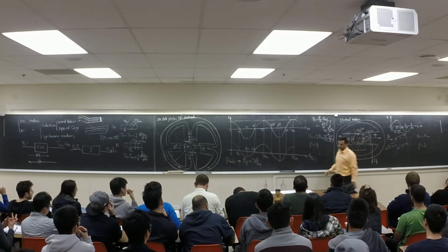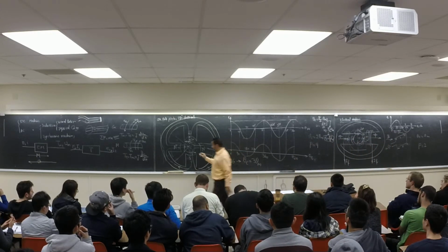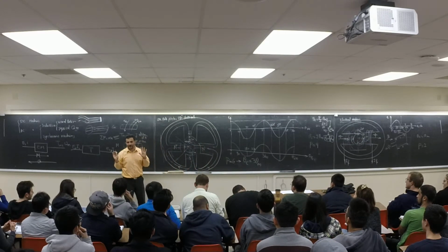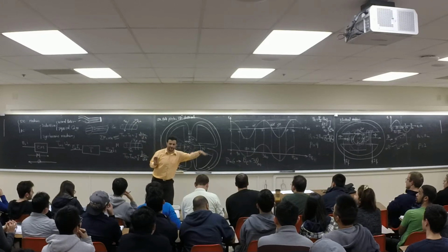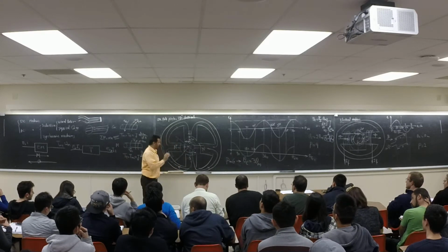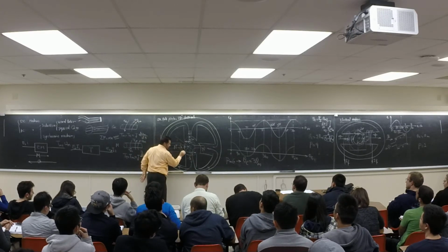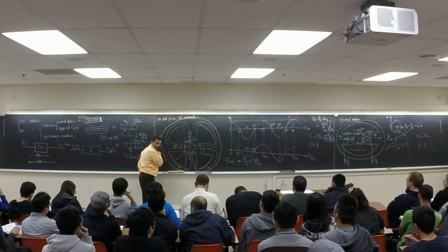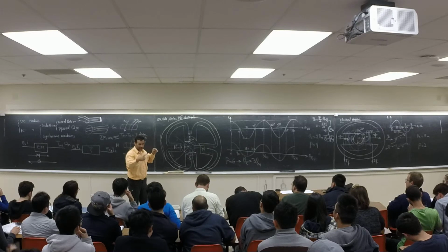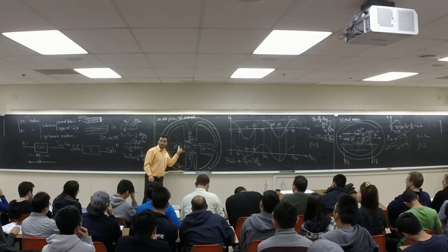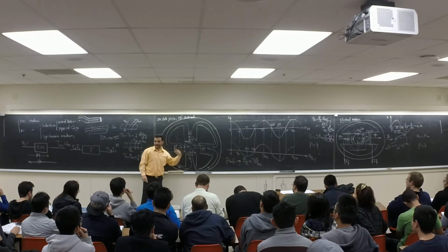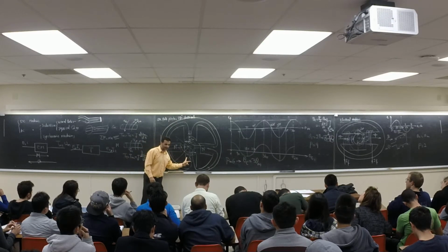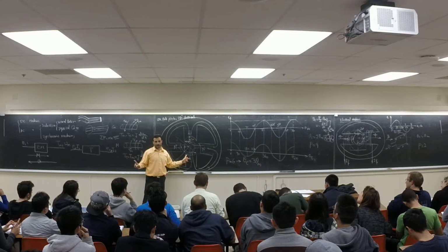How much is the pole pitch here? It's still 180, see, all the time it is 180 electrical. You go from N to S, right? 180 electrical. I'm going from here to here. How far did I go electrical? I went from N to S. N to S is 180, right? But how much is mechanical? 90. If you had a 6-pole machine, one pole pitch is electrical 180 degrees, which is 60 degrees mechanical, right?